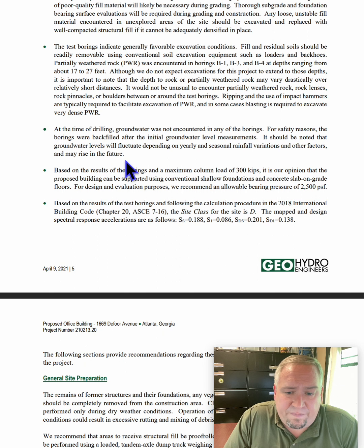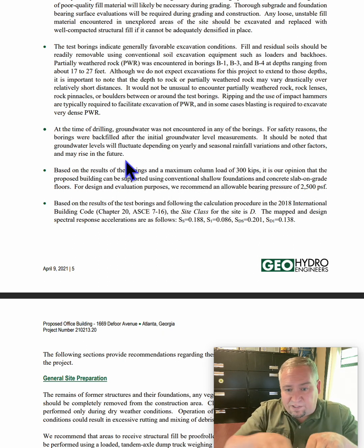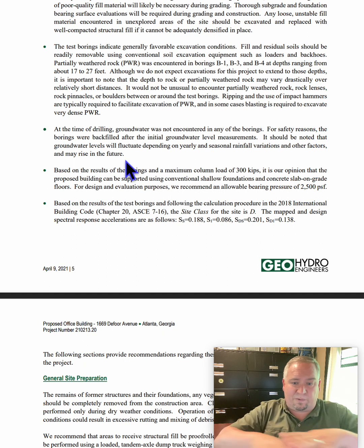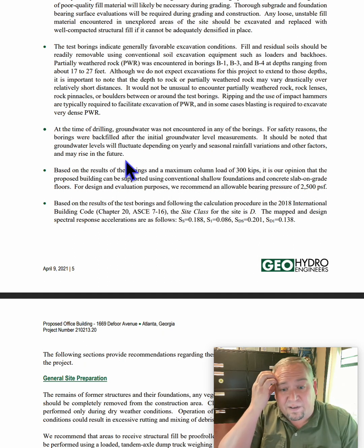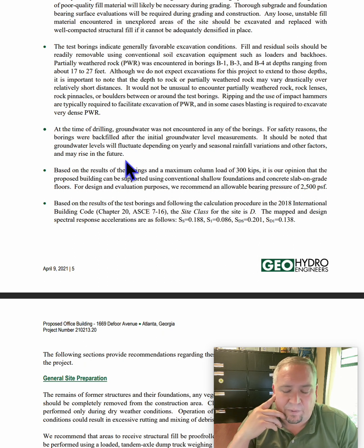The water table is just a consistent level of water that's in the ground. If a stream is at this elevation, it's usually 20 or 30 feet across the board all the way up under there. So if we run into that, then that's the time we have to get pumps and other things out, when we're laying pipe or if we've got a detention system.